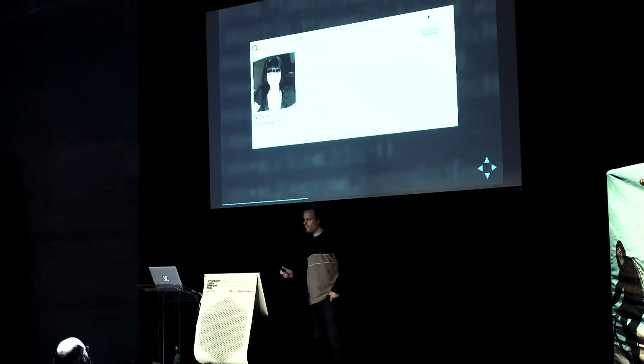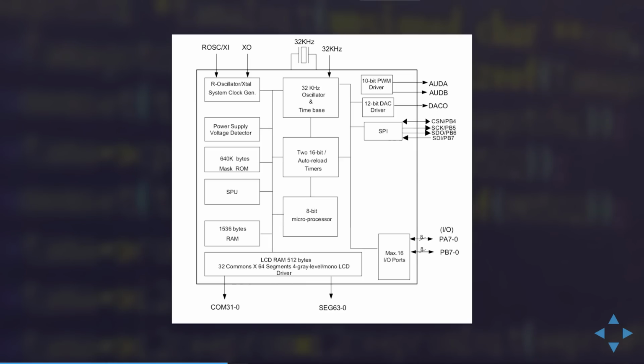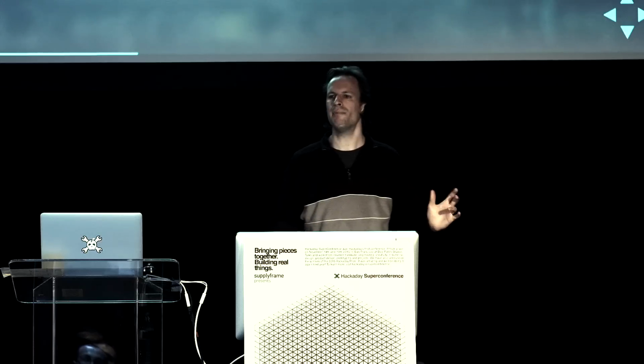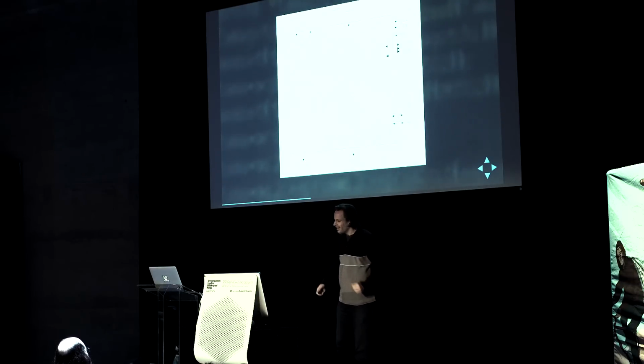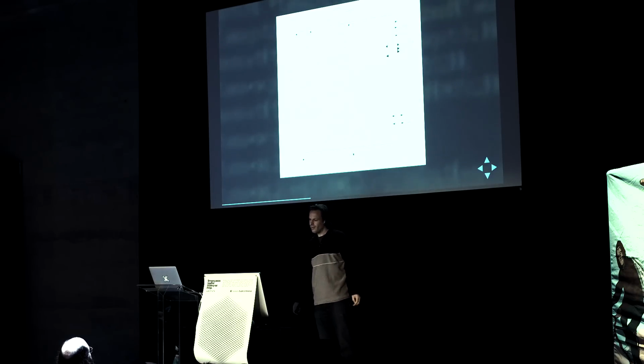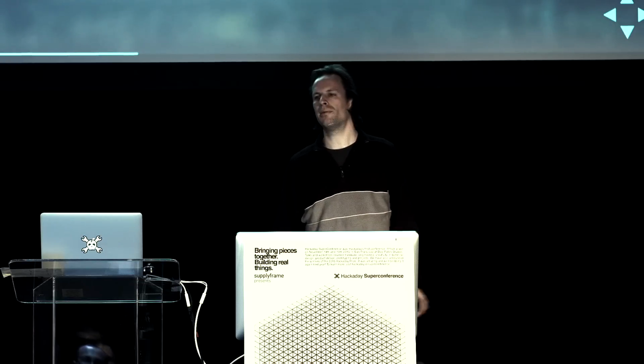So what she found out was that the big blob basically contained a processor made by General... sorry, I forget the name. It's basically a Chinese manufacturer. It's a really simple and cheap processor, as you would expect. Here's a block diagram. It's basically an 8-bit microprocessor. It's a 6502. It has a few timers, it has an LCD controller, very important, it has an SPI port, and a few extra bits and bobs.